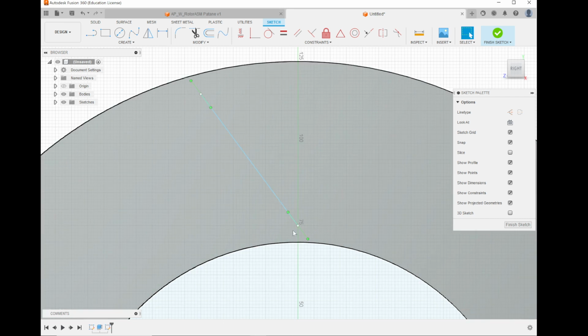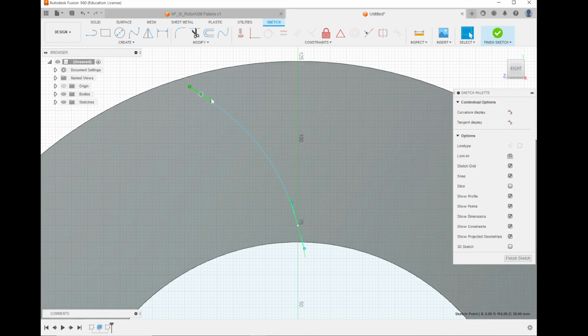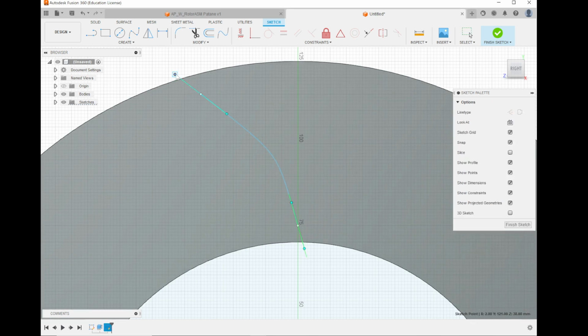Yes. So we can do that by changing this green line, by bringing this down. I can change the angle that the curve meets that point. And by pulling the green further away, I force it to be a larger radius curve. So if you don't actually care about the actual numbers and you just want to make it how it looks, you can just change these green lines so you get a curve that's something you like. Do I like this curve?